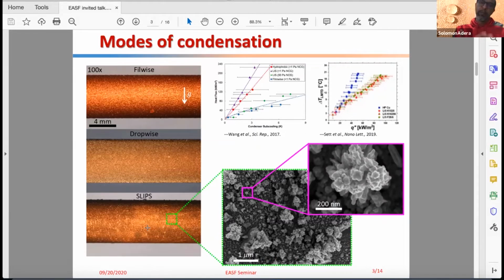The explanation is the same as for dropwise condensation: when the droplets leave faster, at smaller length scales and higher frequency, the surface is exposed to vapor, and therefore the performance improves. This is an SEM image of the nanostructured surface that's impregnated with oil for the condensation experiment.